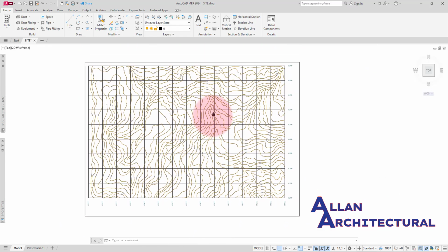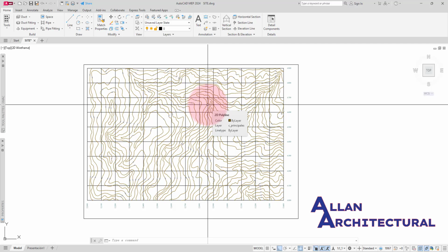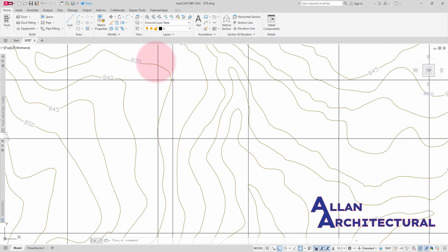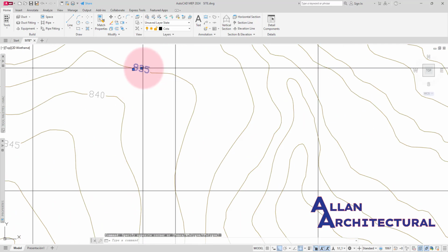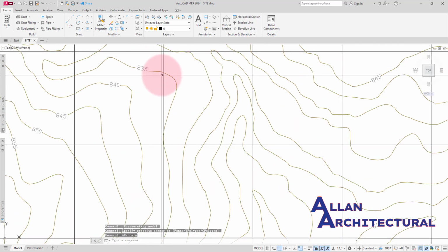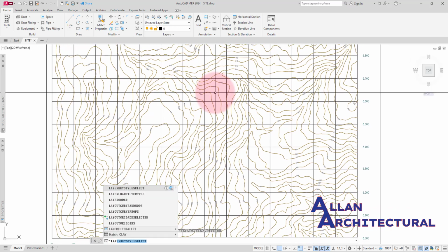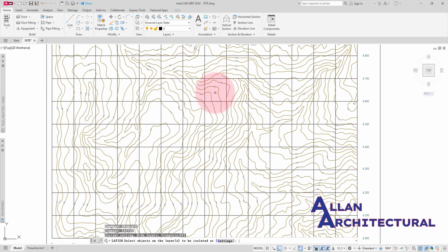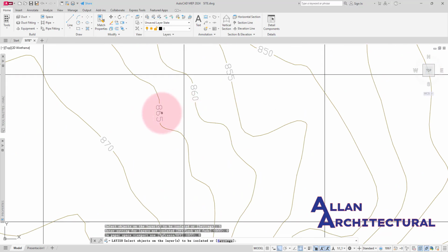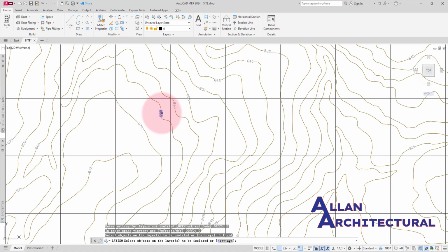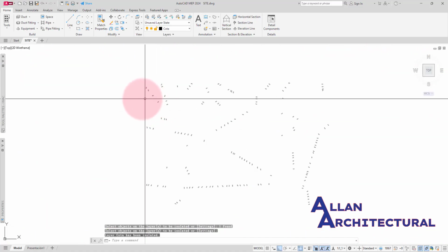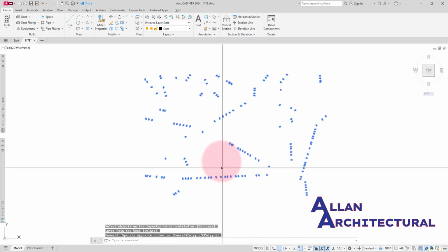All right, so I'm going to get started, and you need to perform a layer isolation in there. What you need to do is select these figures, and okay, let me just escape out of there. Then click on layer ISO, select that, get into settings and make sure you turn that off. You need to select the object you want to isolate, so I'm going to select this and hit enter, and you notice we just have all of these numbers in there.